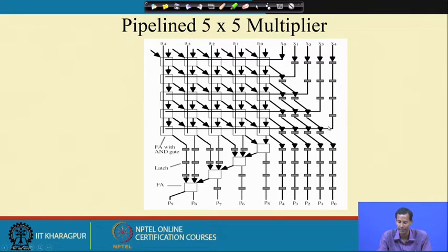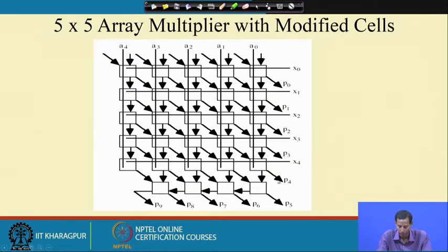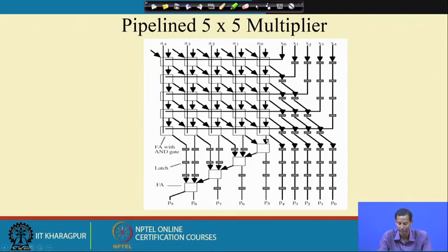That is basically 4 for this, because x4 has been applied after 4. If I go back to this stage, at the very end I again need to pass through a carry propagate adder or ripple carry adder for generation of P5, P6, P7, P8 and P9, as the carry is basically propagating.